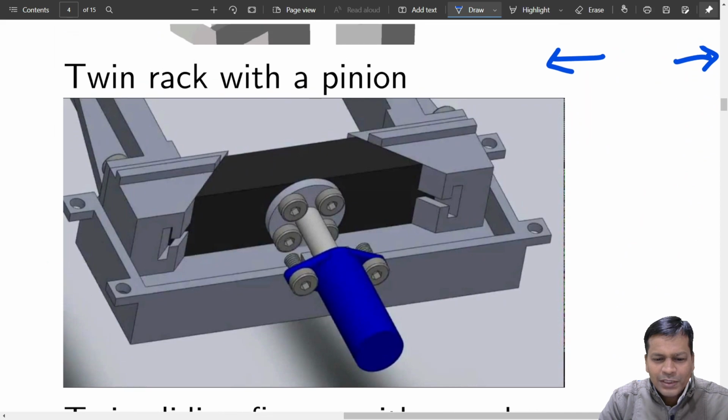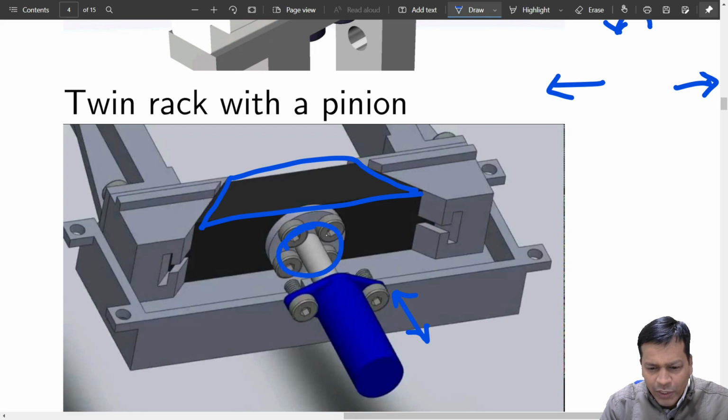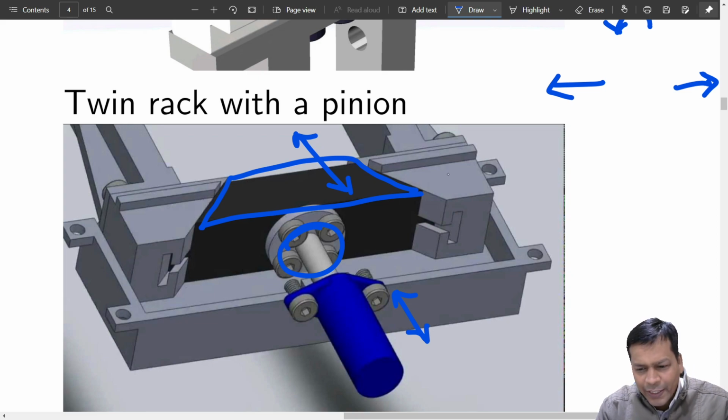Okay, what is this? This is a wedge, right? You can see this is a pneumatic cylinder which can push and pull this particular end so that this wedge can travel in this direction. Okay, it can either go in or it can go out, right? So just one actuator and you have two sliding wedges.